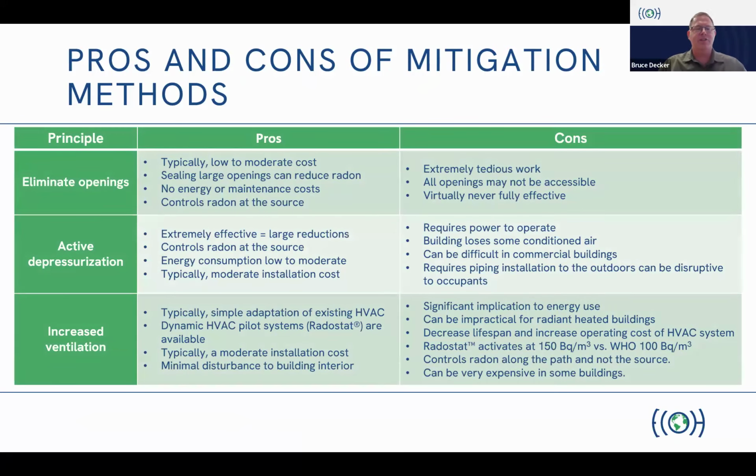A lot of people say, well, let's just seal out the radon. It's never going to happen. It's typically not likely. If you have radon that's a little bit over the action level and you've got a big hole in the floor, like an open sump pit or a crawl space or something, sealing that might make the difference. Very unlikely though. People want to go here because it's typically low to moderate cost. Any handy person can grab a tube of caulking and seal a crack, right?